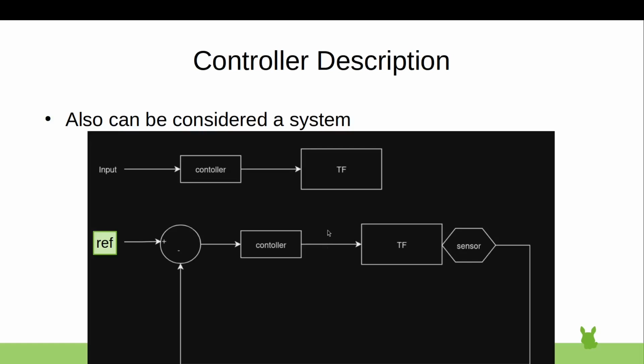And here's basically the open loop, as I've talked about before, and this is a closed loop. And it has a controller. So you would consider this a closed loop controller. And you have a reference here, which is the idealized position of where you would want your system to be. Basically, we have the reference here, and we take the output of our transfer function and we generate an error, and the controller controls it to get to the idealized position of this reference.